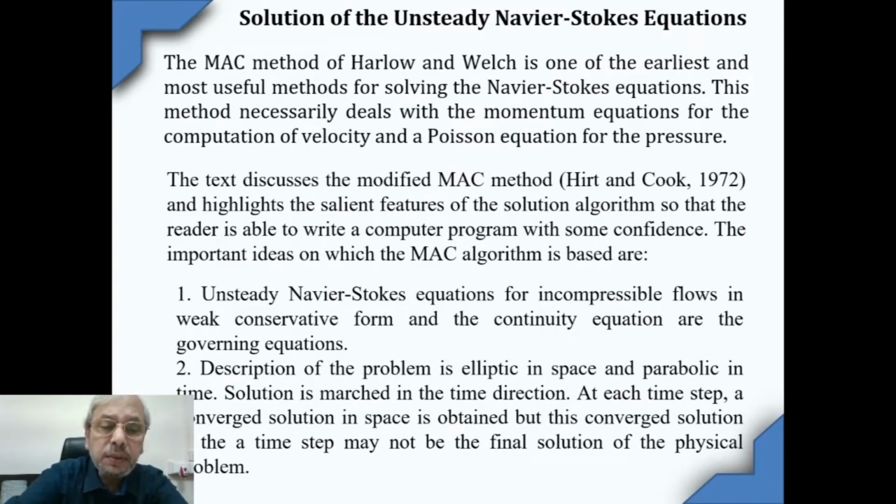Now, this uses unsteady Navier-Stokes equations for incompressible flows, and we use weak conservative form and continuity equation. Description of the problem is elliptic in space and parabolic in time. Solution is marched in the time direction.